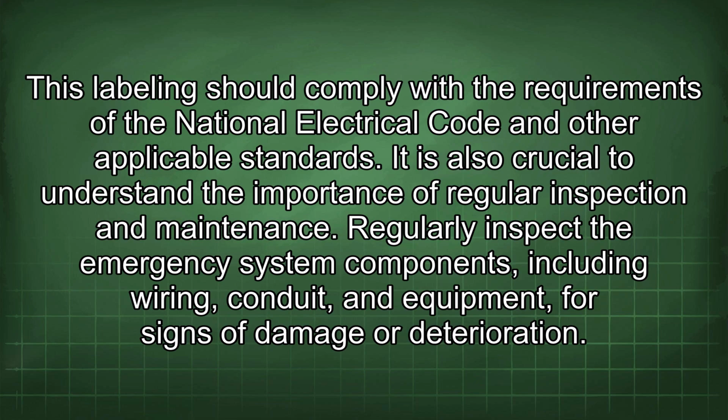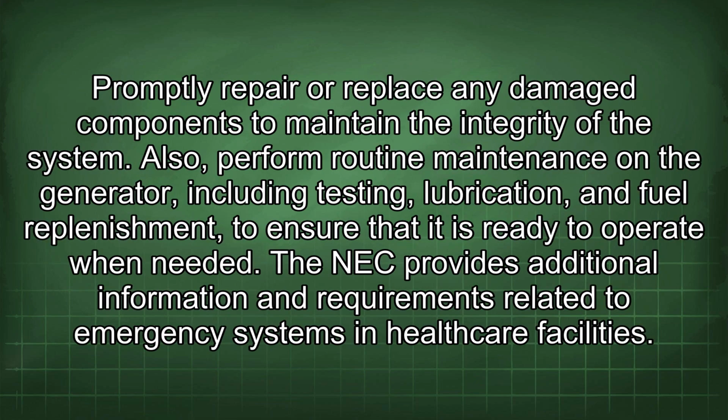It is also crucial to understand the importance of regular inspection and maintenance. Regularly inspect the emergency system components, including wiring, conduit, and equipment, for signs of damage or deterioration. Promptly repair or replace any damaged components to maintain the integrity of the system.